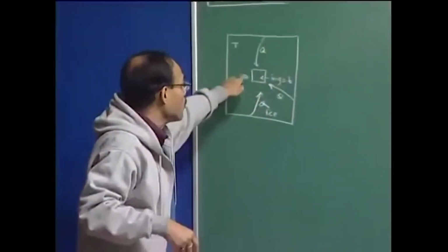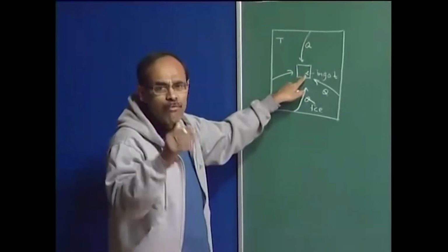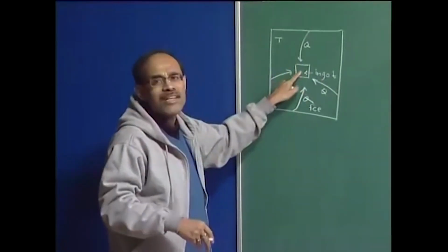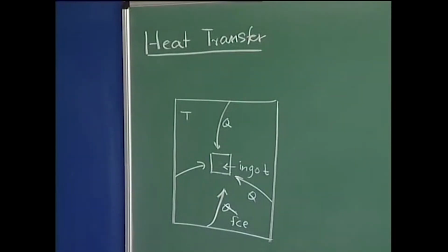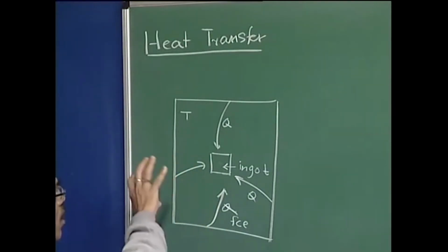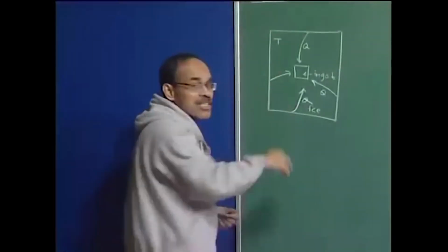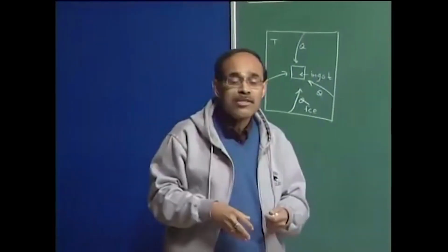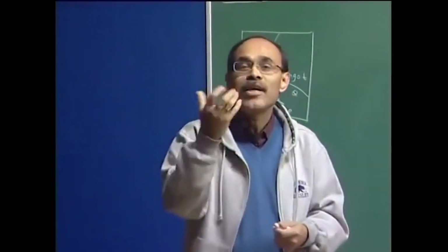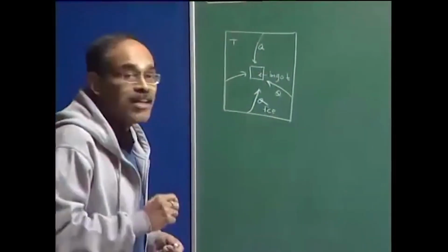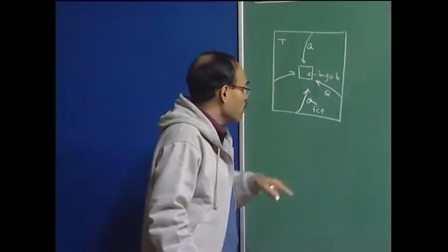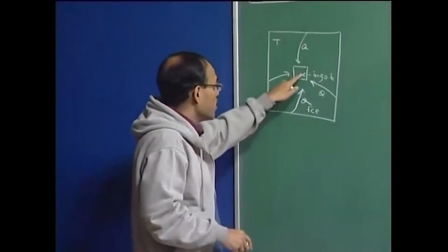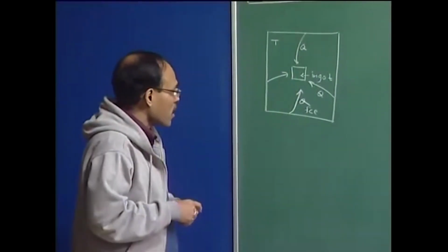So, prediction of complete homogenization time or a uniform rolling temperature in the reheat furnace is of key interest, and unless we know the fundamentals of heat flow within the furnace itself, from the furnace environment to the solid surface, and then within the solid, we will not be able to calculate the optimum reheating time, which essentially gives a constant ingot temperature at the end of the cycle.